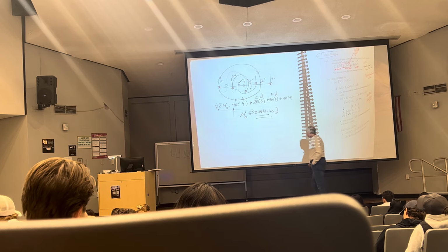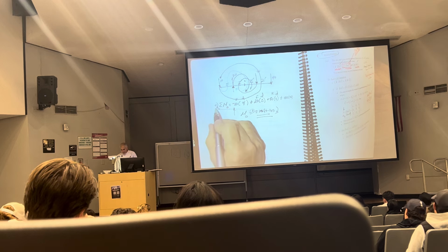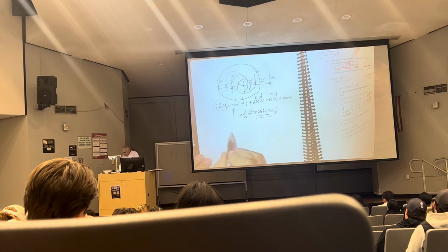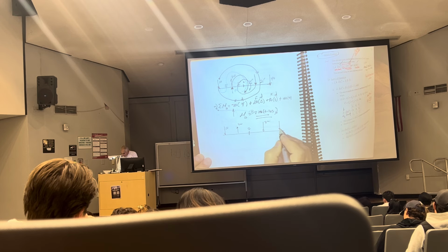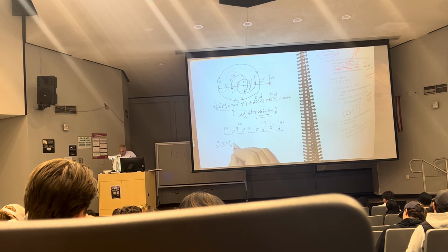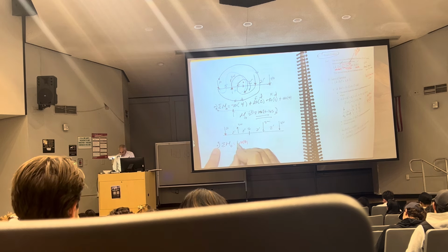Yes? Now let's do it again, except this time, let's do it with some of the moments counterclockwise. So same problem. 10, 20, here's O, here's 30, here's 40. 2, 2, 2, 2. Some moments about O, this time counterclockwise positive. Again, this is 10 times 4, the distance from here to here, 4. Take the arrow, go around O, what do you get? Counterclockwise. Well, that's positive, so I'm going to put a positive here.